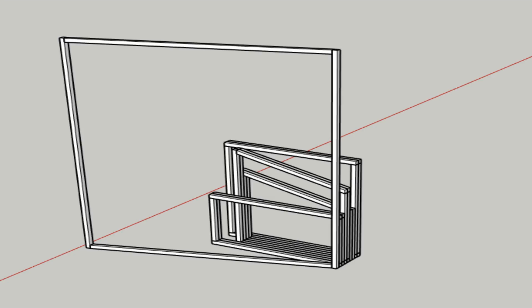Panel splitting. Stacking the current panels will take about 1.5 by 1.5 meters. Except the roof, which is much bigger. The acrylic might bend under wind or under heat differences. Also, the panels will be difficult to handle. A solution is to cut them into smaller pieces.